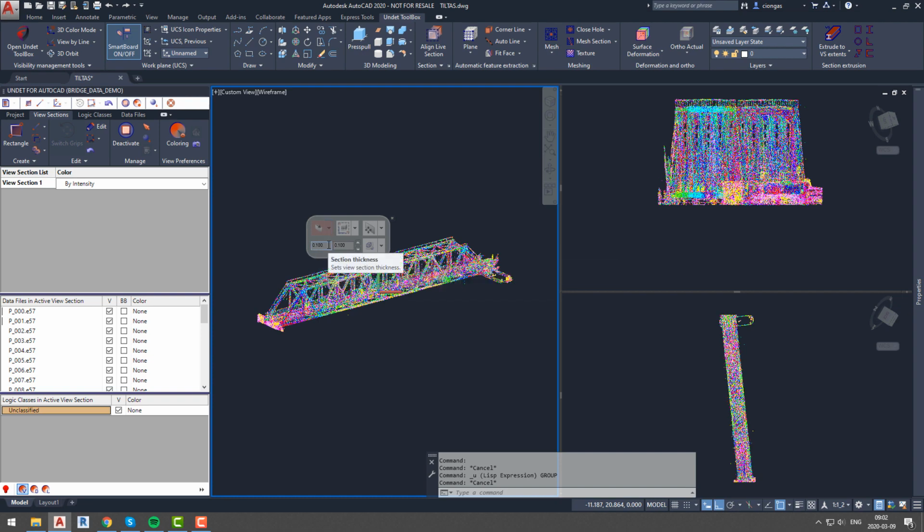cross-section and profile section. Also you will be able to adjust section thickness, section offset size and even move that section using arrows. Another thing that you will be able to do is to change section view in draft plane according to specified surface. Then you have drafting plane management settings. And few more options to translate section view from drafting viewport into new view section, or automatically create a regular